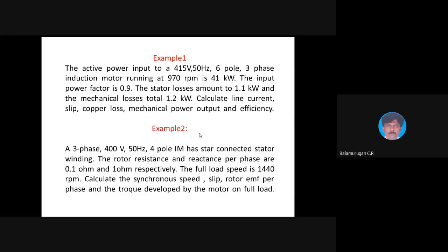Okay, Venkatesh, you continue with the second subdivision. So what is the value for slip? If the synchronous speed is not given in the problem, you can calculate it, or you may already know it. Frequency will almost always be 50 Hz. So if 2 pole is given, you choose 3000 rpm as the synchronous speed. 4 pole means 1500, 6 pole means 1000. So you can use these constant values and substitute them in the place of ns based on the number of poles.